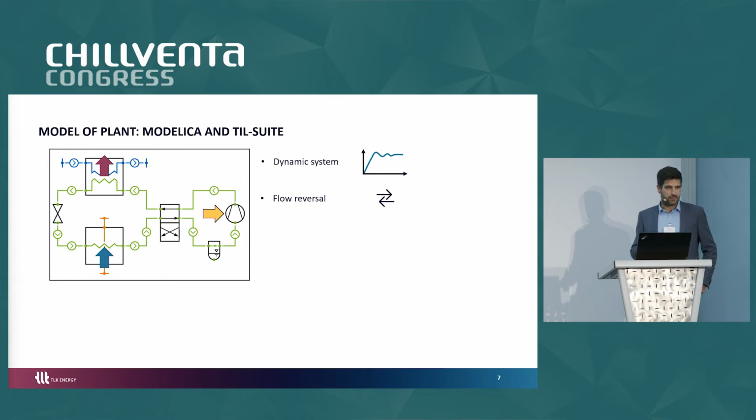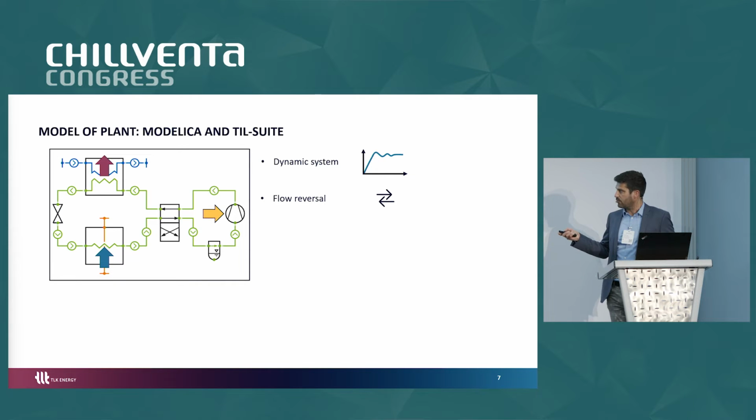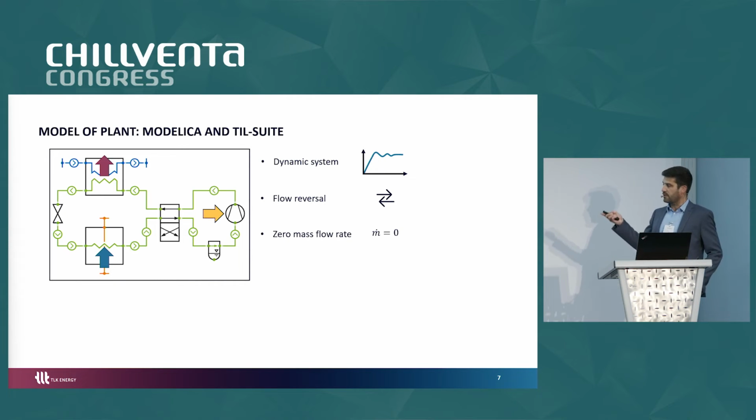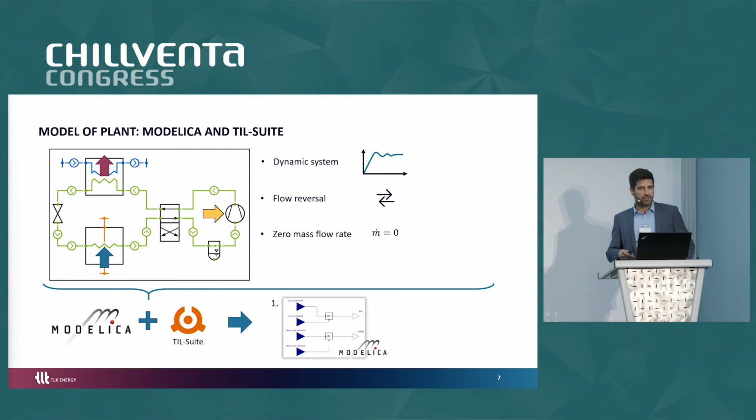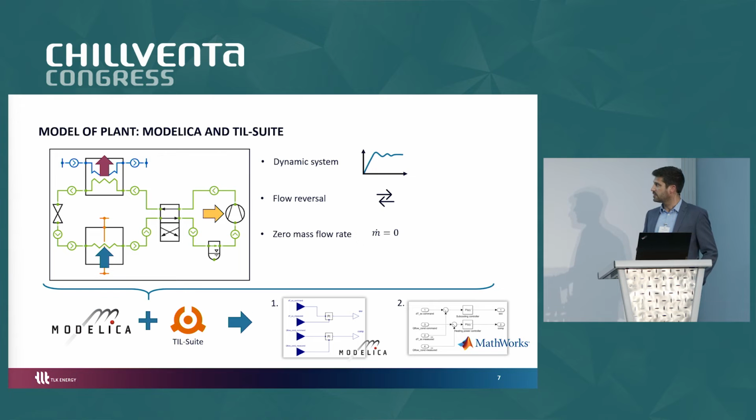We use Modelica as a modeling language, and we have a model library, HiL-testing, that we use for modeling this whole setup. And when we have this model, first you can start to write your controller in Modelica and perform some tests. But when you want to go the whole tool chain, MATLAB Simulink from MathWorks is a good idea to use and write your controller there, because with MATLAB Simulink you have good possibilities to export your code later on to the real hardware.